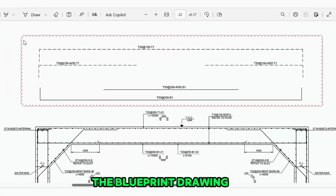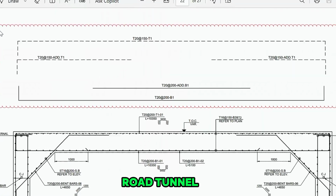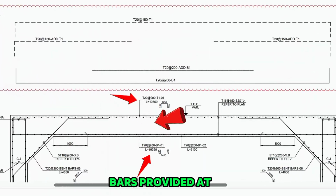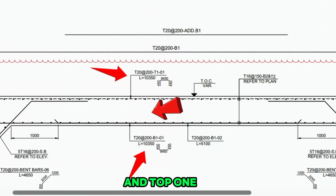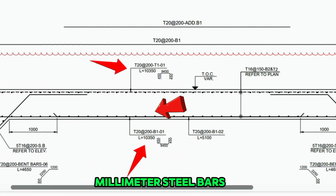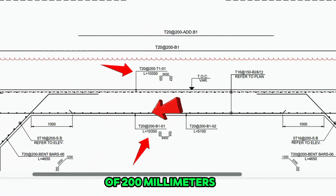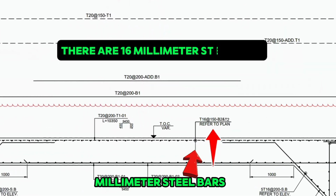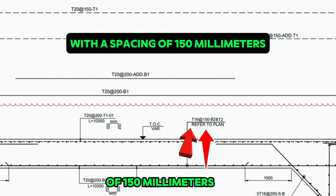Now let's review the blueprint drawing for the underpass road tunnel top slab reinforcement details. The slab has the same steel bars provided at bottom 1 and top 1, which are 20 millimeter steel bars with a spacing of 200 millimeters. At bottom 2 and top 2, there are 16 millimeter steel bars with a spacing of 150 millimeters.